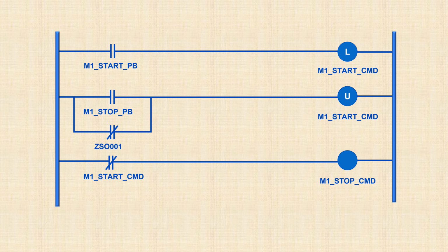Now we will create a PLC program in ladder logic format. This is a very simple ladder logic. And if you're familiar with ladder logic programming techniques, you could immediately observe that the start button will start the motor and the stop button will stop the motor. However, the valve limit switch should show the valve is open, otherwise the motor will not start. This is very simple logic, and you must be wondering that this should not be a problem in developing a PLC program in this way.